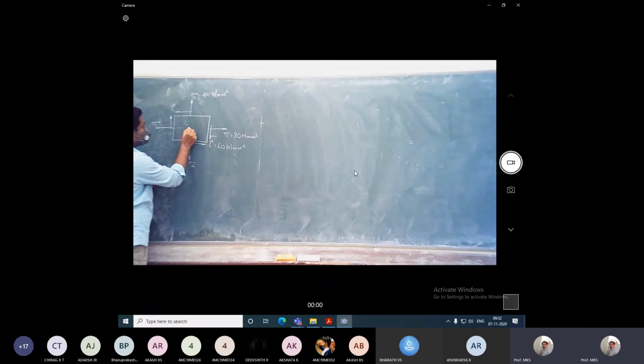So this is the axis of major stress. This will be the axis of minor stress. So this is inclined at 45 degrees. The angle of the plane is 45 degrees. So you need to find the stress along this inclined plane, that is, normal, tangential, and resultant stresses. These values are directly given. You need to use the derivation, that is what we have done. The equation for normal stress.